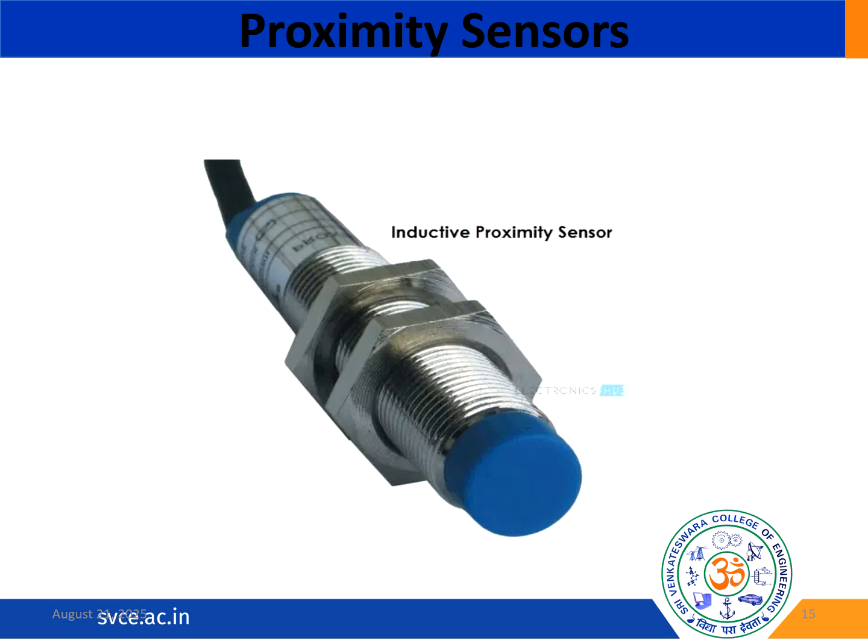When you consider this type of sensor, it is a type of oscillator which generates an electromagnetic field. The target object can be a metal. When it enters the field, it induces eddy currents. These eddy currents alter the field and trigger a change in the output. The sensor sends a signal to the controller. There is no contact required for this type of sensor.